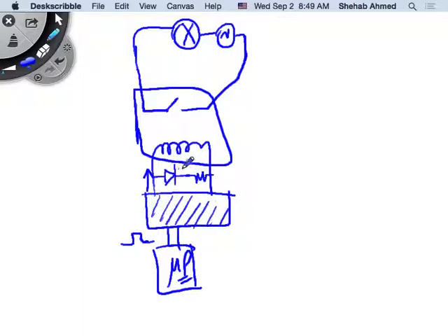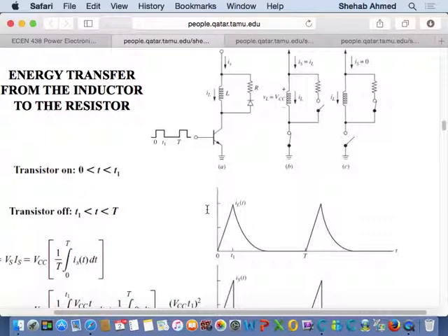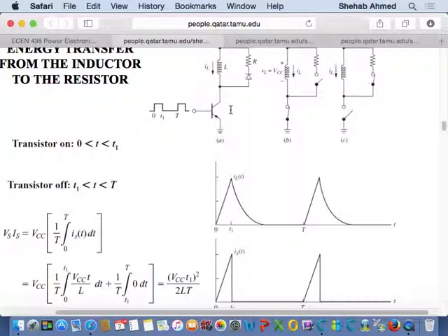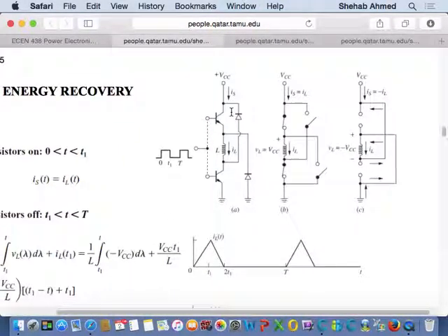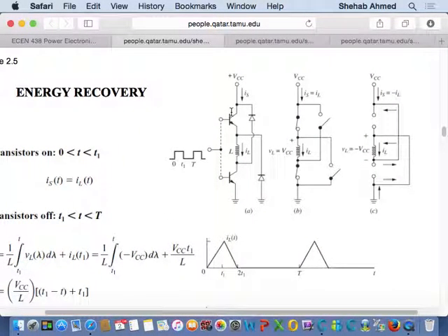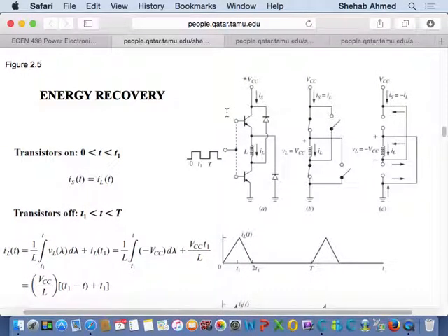So you would typically have a diode and a resistor circuit around any inductor that you charge and discharge, right? Just for freewheeling the inductor energy. That's what it's called. It's called freewheeling the inductor energy, allowing the inductor energy to be dissipated in the resistor. So this is an example of a circuit like that. So people in power electronics did a lot of, this freewheeling business helped a lot. The power electronics people developed many different kinds of circuits.